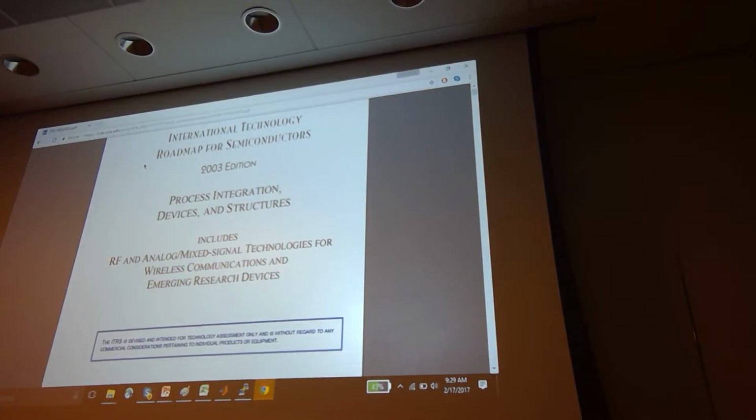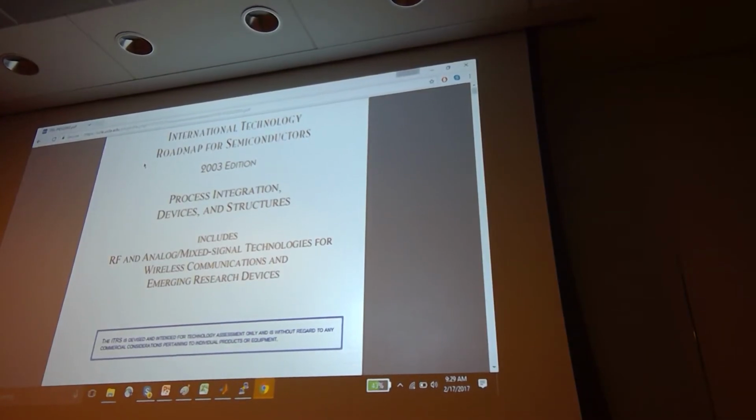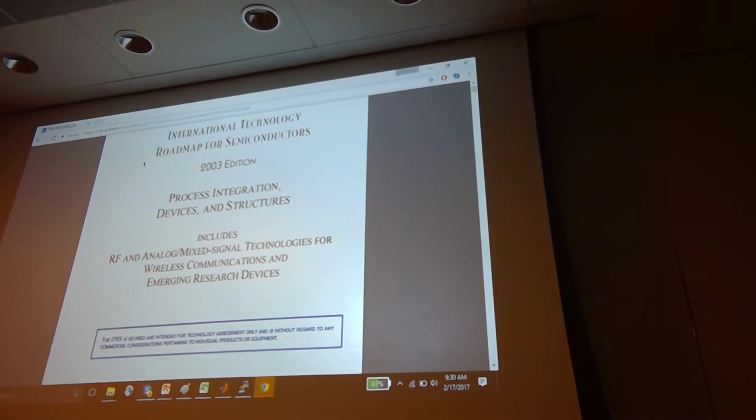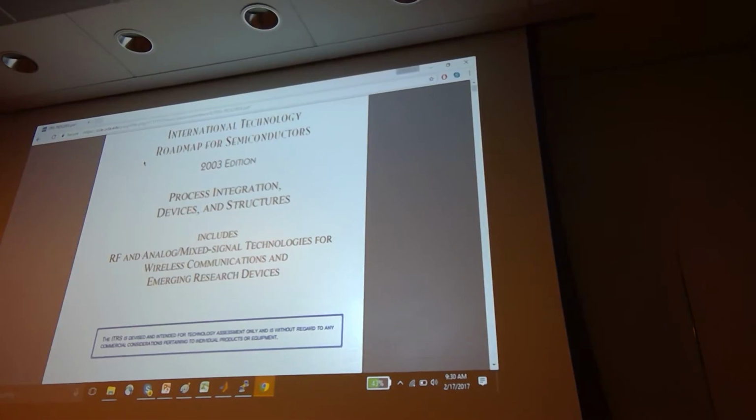No, but see, if we give you the layout, then everyone's layout would be the same, and you guys would probably figure out that all of your processes will almost be the same. So we want each one of your processes to be different. You can always place transistors in different ways, right? So we want to see how well you're able to pack the transistors and how much you're able to decrease the overall size of the entire test transistor, and then design your process accordingly.